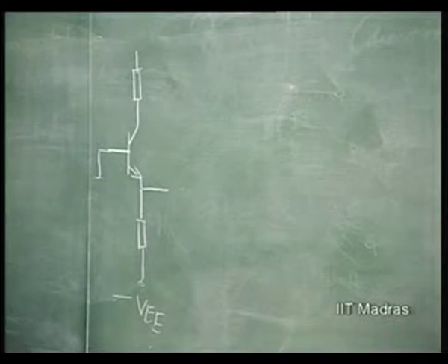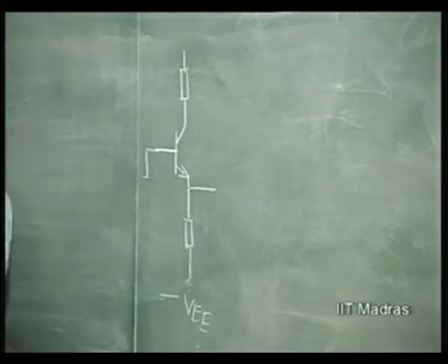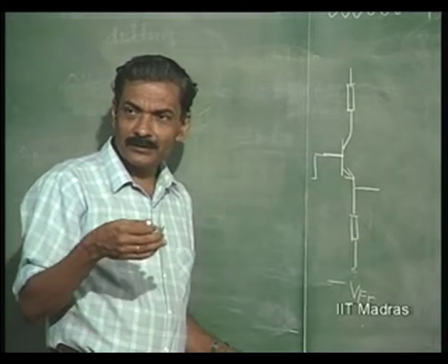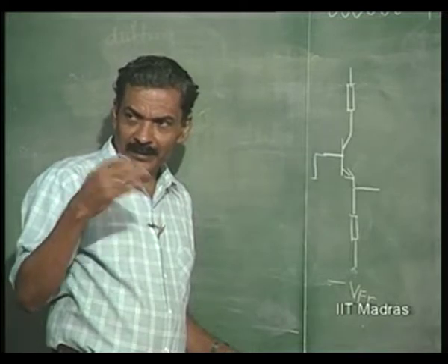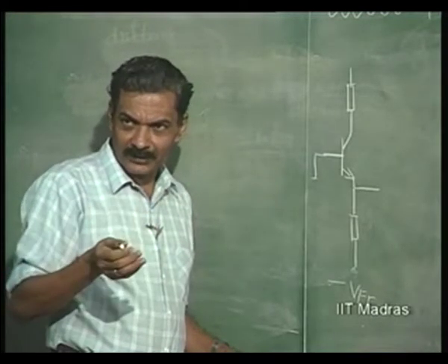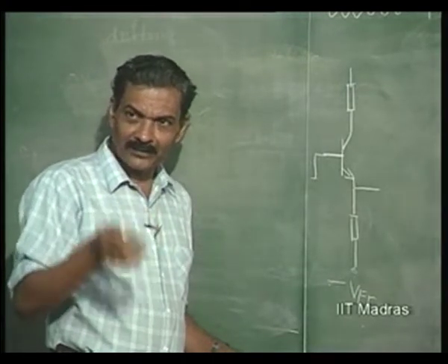We would like to use, in place of these capacitors, components which are readily available in integrated circuits, that means transistors, diodes, and resistors, in that order. If you can get rid of a capacitor using transistors, diodes and resistors, you should do it. If you can get rid of a resistor using transistors and diodes, you should do it.